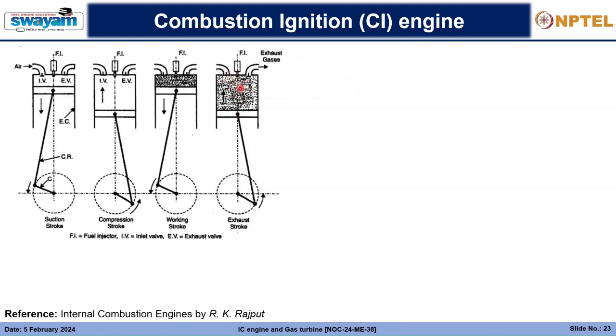So here the energy which is still not utilized completely by the piston or in rotating the crankshaft, the thermal energy or the hot gases, moves away. If the temperature of the hot gases were reduced to the ambient temperature, then all of the energy would have been used up in the working stroke, but that is not the case. There is some heat rejection, so we'll have to live with the heat rejection. You cannot avoid it, so there is an efficiency associated with that.